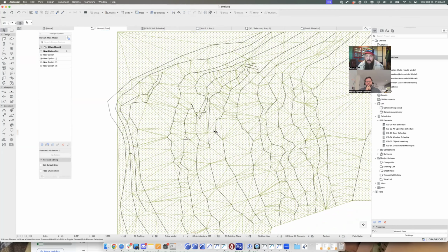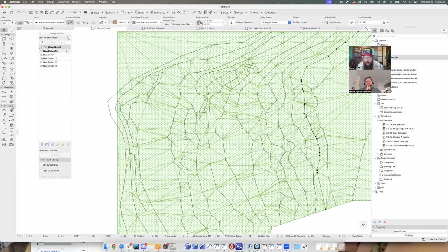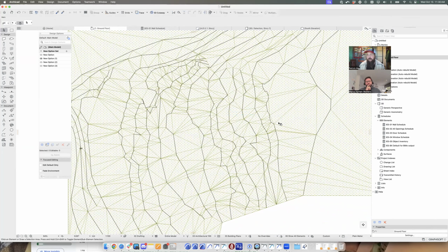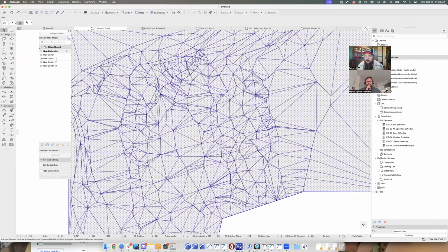So then in 2D, I might need to come back and be like, oh, what contour elevation did that say it was at? If it was really supposed to be 106 and this was 106, then I do have a flat spot through there. So some combination of what's shown in 2D, what's shown in 3D, make it look right in 3D, verifying 2D kind of process.